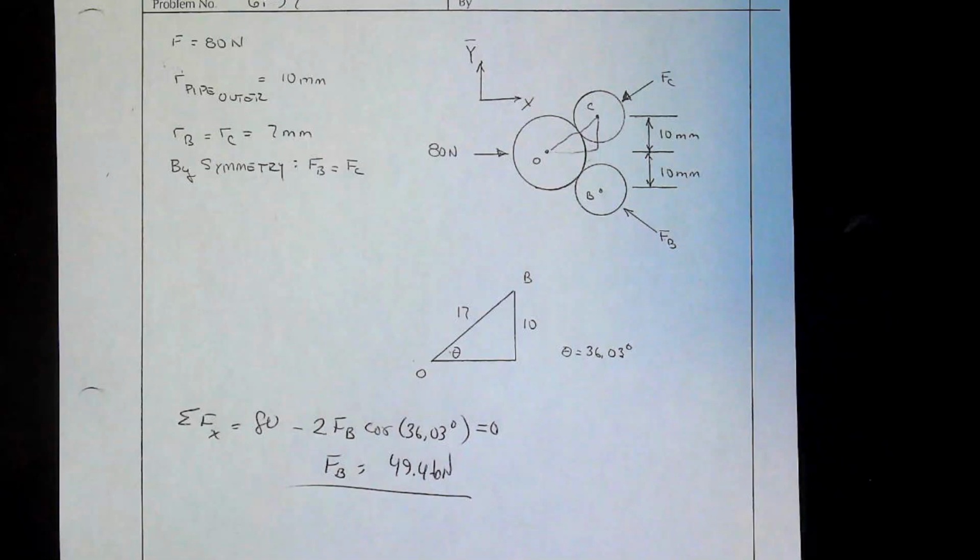So here's this bar. All right, here's the engine coming off of it. If we go look at the geometry, basically this is up 3 meters and over 1 meter. So that's what that's showing. So that's a 1, 3, the square root of 10 triangle. All right, and then on the other end of this bar is this pin joint here. So I have the forces for EX and EY sitting there.